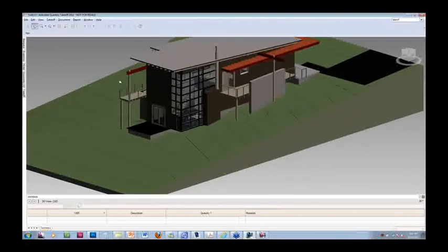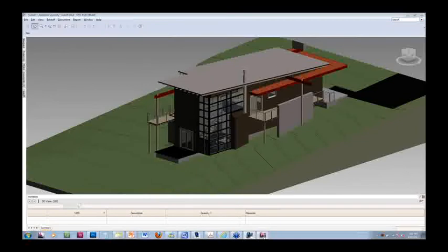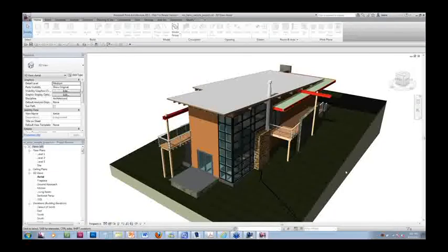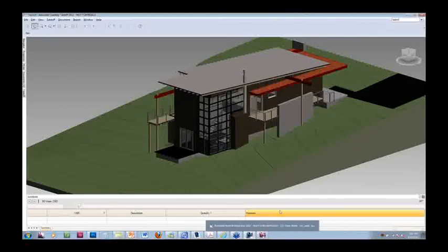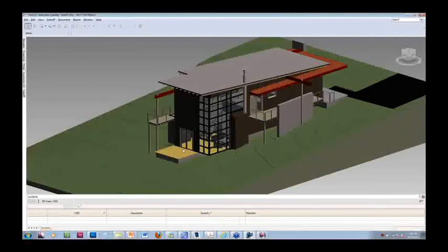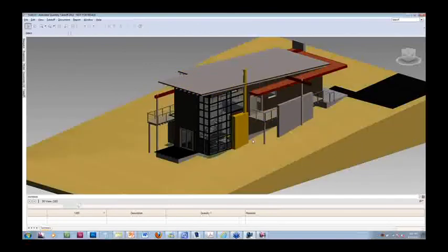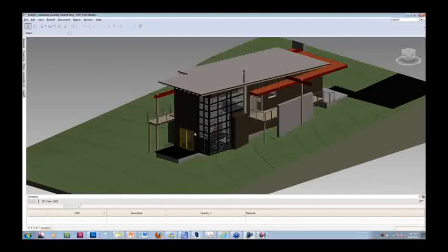It does make a difference seeing things live and almost identical to where it came from within Revit. So this is Revit, this is QTO. So again, the good thing about this is that I have the ability of selecting everything in the model. So if you notice, in 3D I can highlight that wall, I can highlight this roof, I can highlight this particular component. Anything that I grab is going to give me information about it. Also, I can select and track things from here just by applying one of the tools that I have above my toolbar, like the search takeoff or the single click takeoff. But before I get there, let me just show you a little bit of how this works.